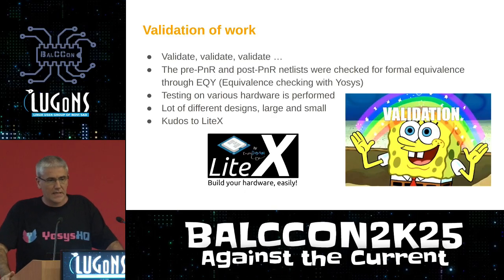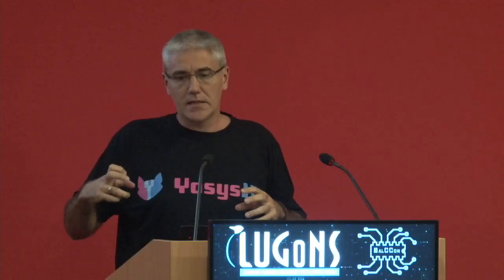So what we are using is the Equiv tool that is used for equivalence checking, and we are basically running equivalence between the input and output. That works for smaller designs, but you can then be sure that you at least have packed things correctly, and that if you are changing some logic or optimizing, you didn't affect the bitstream and the logic at all. And you again need to try that on the hardware, because it can sometimes not work on the hardware,